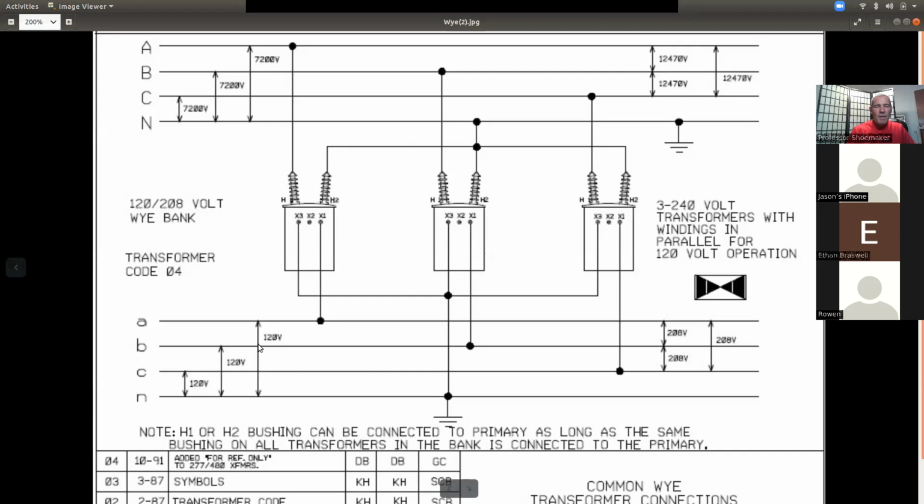The voltages are very easy. You get the individual output of every transformer, 120, 120, 120, and combined, all three are 208, 208, and 208. It tricked you. Closed delta and open delta have lighting transformers and power transformers. Closed delta and open delta. Y does not.